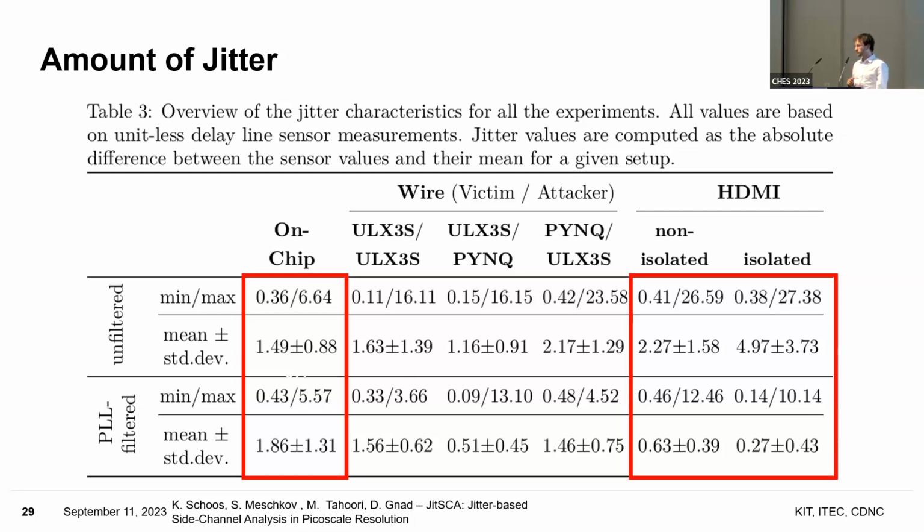You didn't, for example, connect it to an oscilloscope and then let it run and sum up all the clock and then see how much they really differ? Actually, if you think of it, our TDC is roughly sampling at 80 gigahertz. Our oscilloscope is not that fast. With a 1 gigahertz oscilloscope, you see absolutely nothing. Maybe we had a 4 gigahertz oscilloscope, so maybe the extreme cases of jitter we would see, but everything else would also be nothing. So this is actually a very small timing difference. Okay, very good.